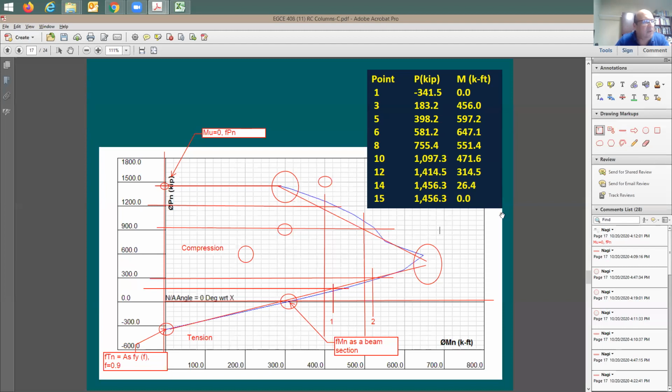You guys know this, right? Epsilon C, what does this E mean? The strain, which is epsilon, C is going to be equal to 0.003. You guys know this, right? Yes. This way we consider the concrete to be failing when the concrete strain approaches 0.003.